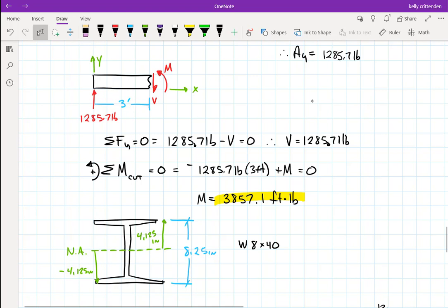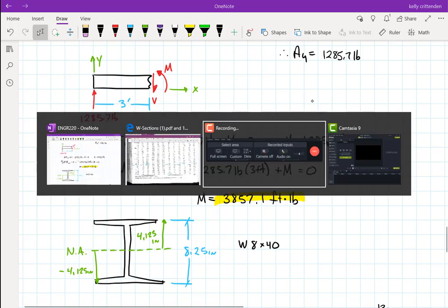You know, where's the bending moment, M maximum? What number is the maximum value I can put in for I or for Y? Actually, I should not change. The cross section of the beam shouldn't change from one end to the other, so I should be constant. But M and Y might change depending on what I'm looking at. So that's what we're going to do next time, is how do we figure out where the maximum bending moment is. So there's ways to do that. But I think for now, we have enough information.